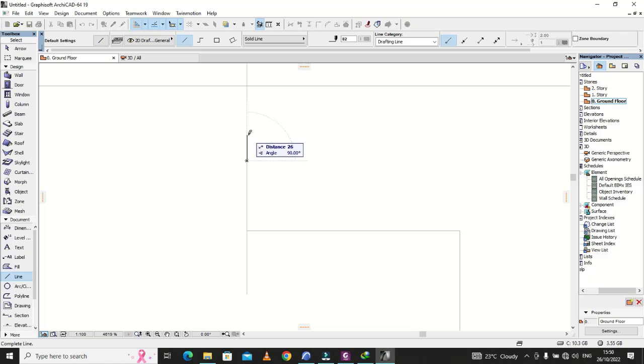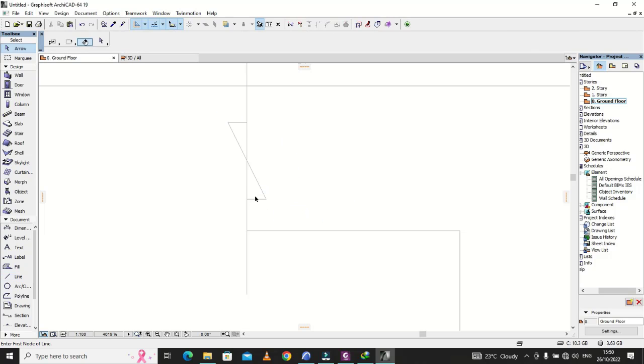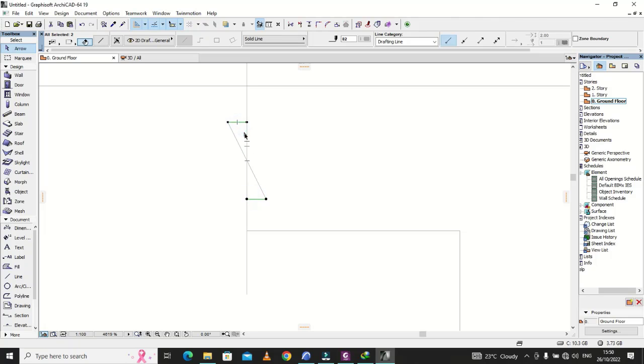We go in this direction 30, then in this direction 40, and in the other direction another 40. This one shall come this way, say it be 20, then this one will be 20. Then join the two like that. Select these two lines and trim what is in between.